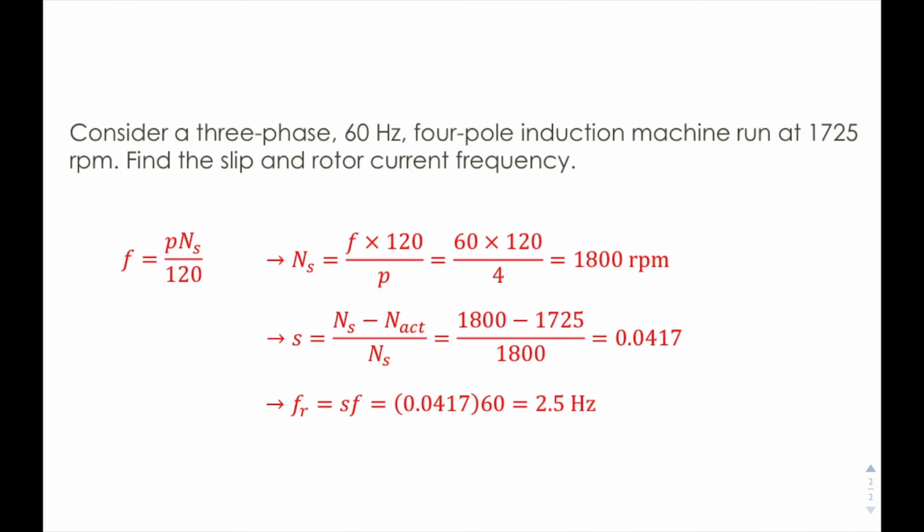We will now show you a simple problem involving induction motors. So first, we're going to use this formula seen below to find the no-load synchronous speed. And so we plug in the 60 Hertz frequency and the 4 poles that were given to us in the problem onto the P. That then gives us the 1800 RPMs. And we use this value for finding the rotor slip.